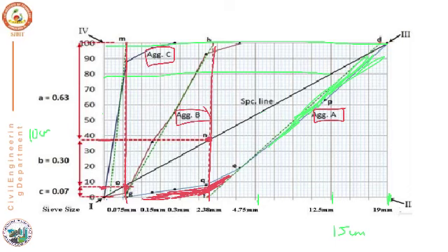So now you have got the distance for the first line, which is 0.07, that is 7%. The second is around 30%, 10, 20, 30, and the remaining 63% for the other material. That means to get the required gradation, you have to take aggregate C of 7%, aggregate B of 30%, and aggregate A for 63%. So now how will you consider this?